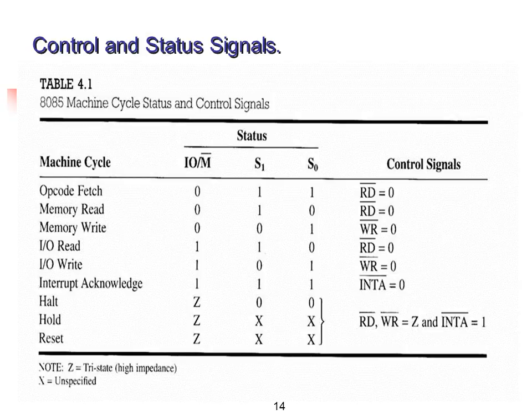Auxiliary carry flag is set when the carry is forwarded from bit D3 to D4, and the parity flag mainly depends on the result of ALU. If the result of ALU has an even number of ones, it is set to 1, and if the result of ALU has an odd number of ones, it is set to 0. Carry flag is set on the carry.